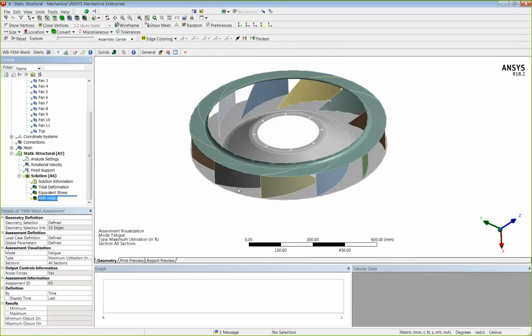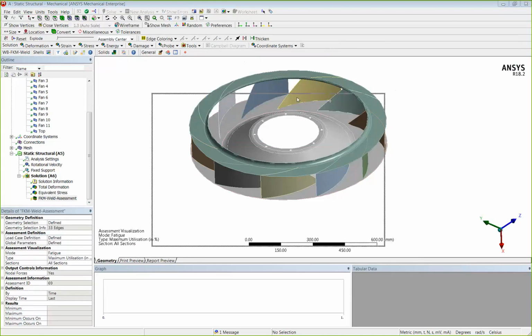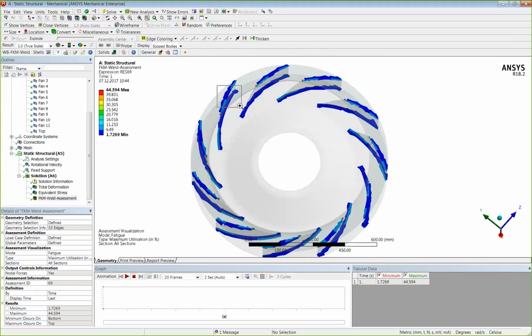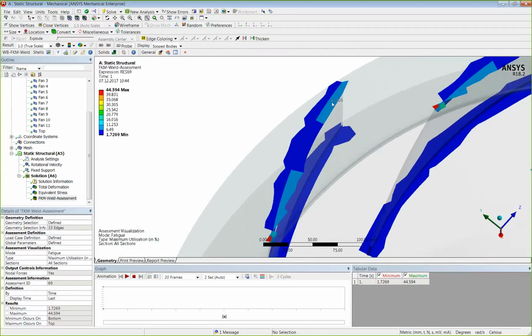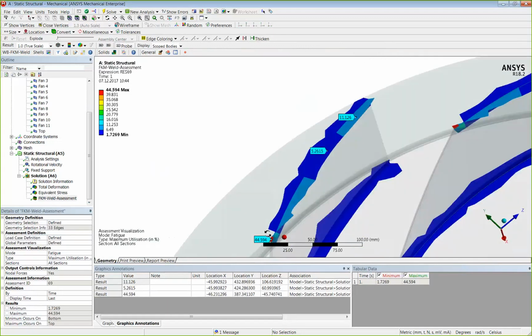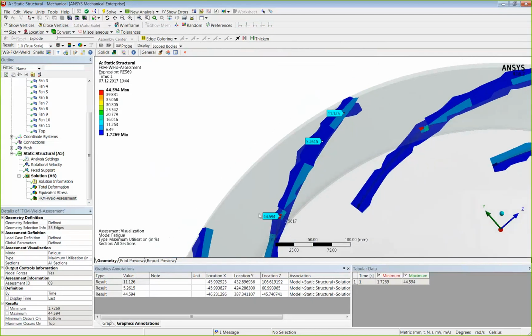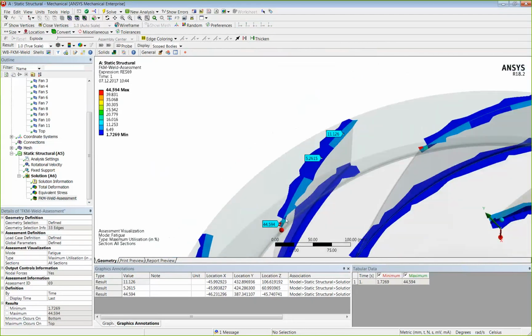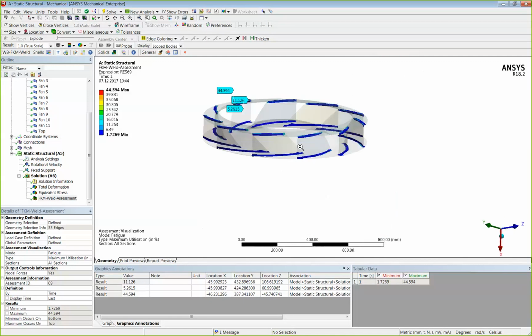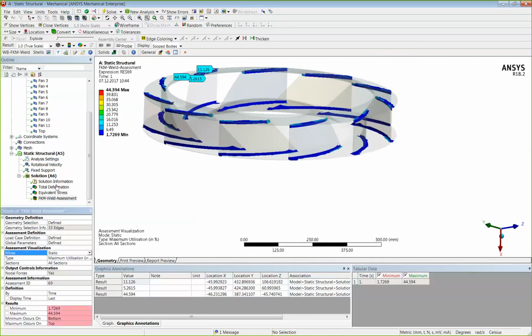And what I get now is, it will again calculate. And what it will do is give me one result for each segment. So I have 11%, 5%. I have very small segments right in front, and I have higher stresses here. So I have 44% degree of utilization in this foremost area. Good. What I could do for fatigue, I could also do for the static.